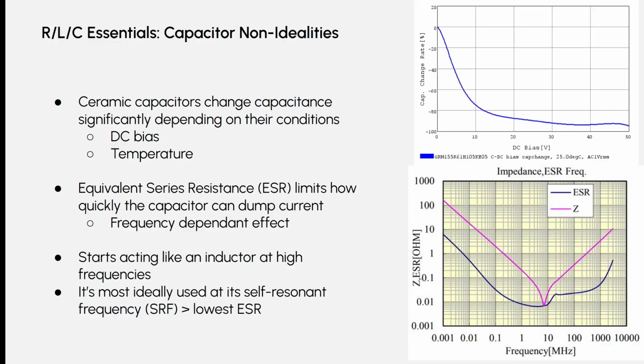But if you have, let's just say, 100 volts as your base voltage, and then some sort of AC signal flickering around 100 and 101 volts, there's a DC bias there, right? It's not moving over the full range, but it is offset from 0. And that can make capacitors lose capacitance very quickly under that effect. Based on this graph, which is a rough example, if you have a DC bias of even just, let's say, 20 volts, your capacitance could be as bad as 90% less than the rated amount.